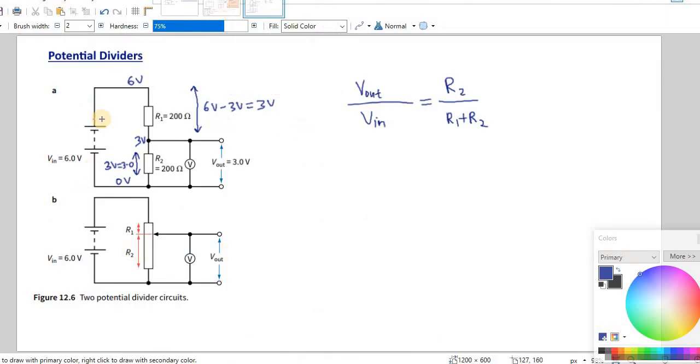Alright, so here I have put it in a way that is easy for you all to understand. Look, from here, like I mentioned before, up to here it is 6 volts. So that's why I have written here 6 volts. So the potential here is 6 volts. Now why I am telling this is, there was a question in one of the past exam papers where they had asked this question, and when you go across this resistor, because there is a resistance only, the potential drops from 6 volts to 3 volts, it drops here.